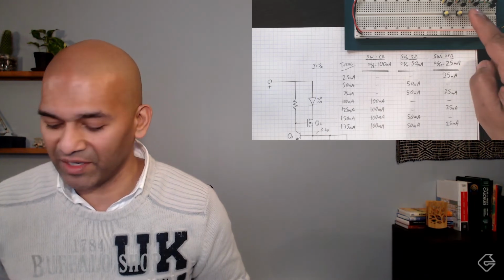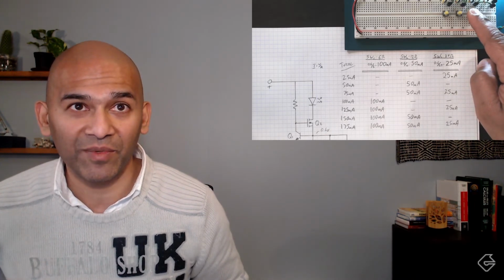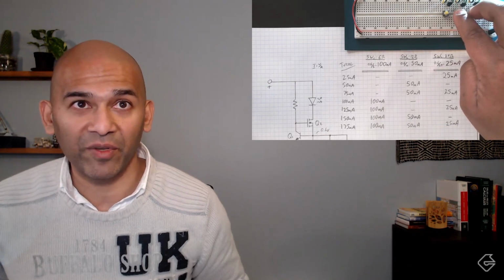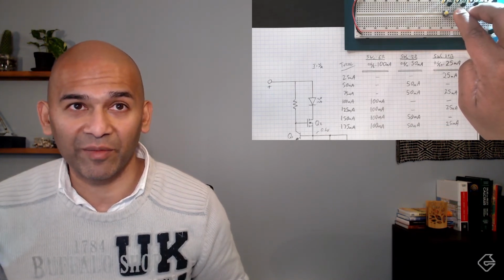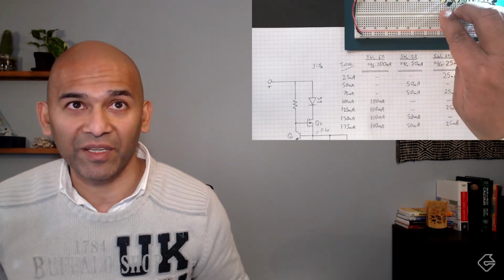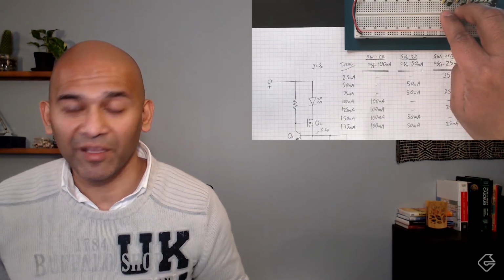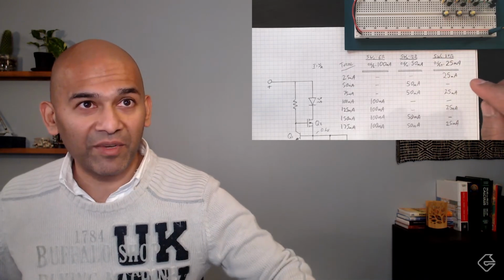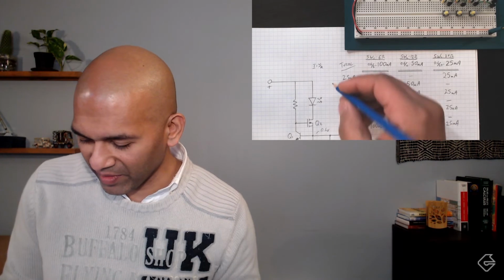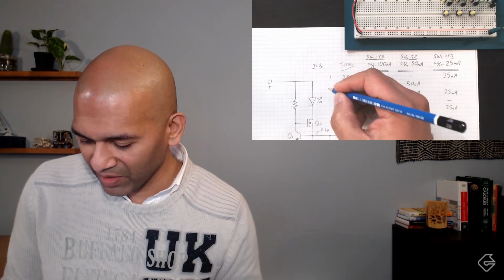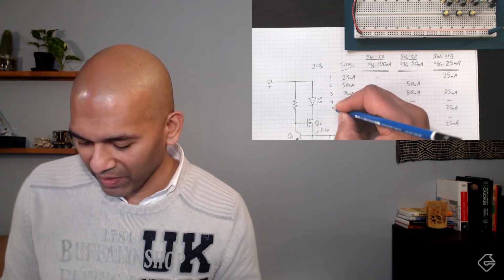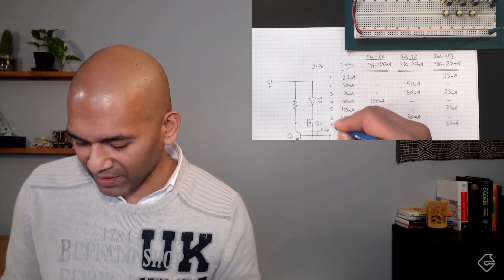So this is going to give us presumably 25 milliamps. If I put this one, it's 50. And if I put them together, it should be a little bit brighter at 75. And then if I get this one, it'll be even brighter. So let me do them in order. In fact, what I'll do is I'm going to number these, actually. Let me number them. So I'm going to number this 1, 2, 3, 4, 5, 6, 7.